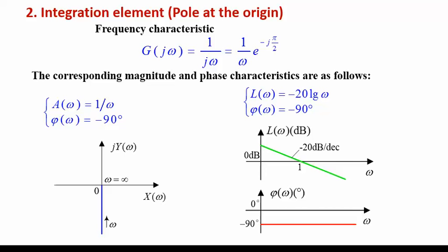The magnitude now here, the corner frequency is omega 0, in this case 1, because omega over omega 0 is 1. When omega over omega 0 is 1, what is the magnitude? 0. Log 1, log 10 to the power 0, is 0. Right?